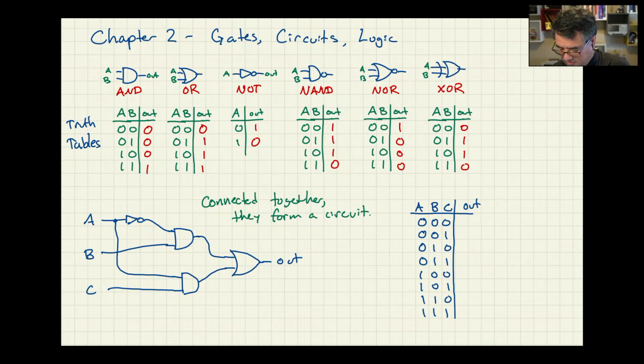So you can basically think of the inputs as data going in to this circuit from the left, and then they flow through these other gates, and then they come to the output over here. And so to figure out what the values of the truth table are, you kind of just have to work through all of these 1s and 0s and watch the values flowing through the circuit. So let's start with all 0s, which is the very top row of the table.